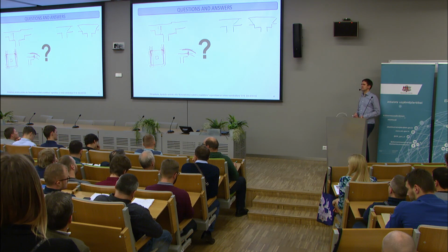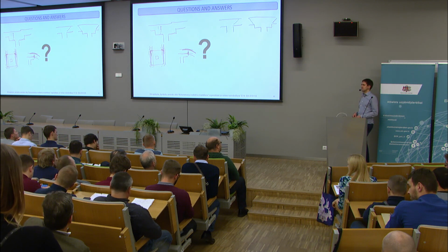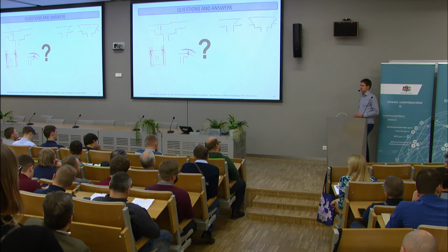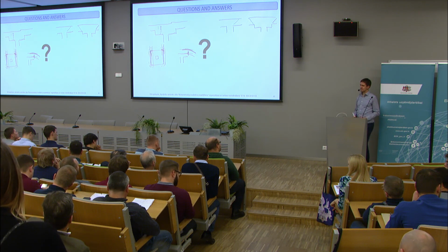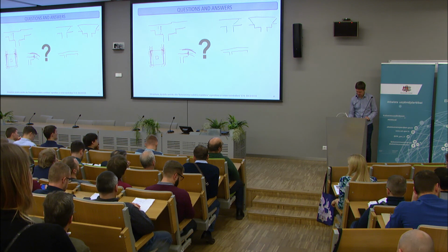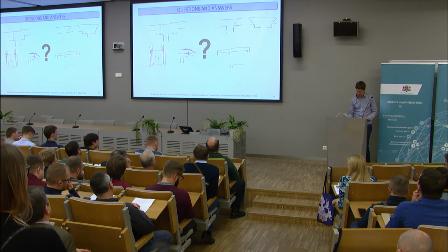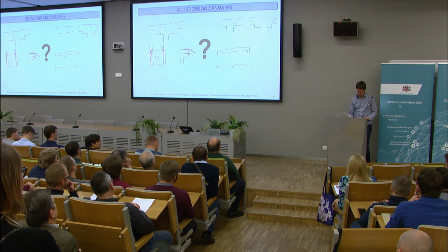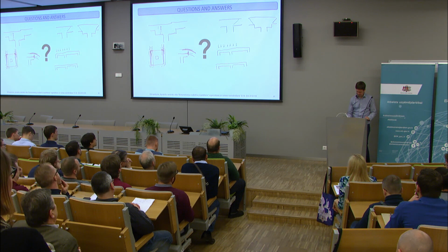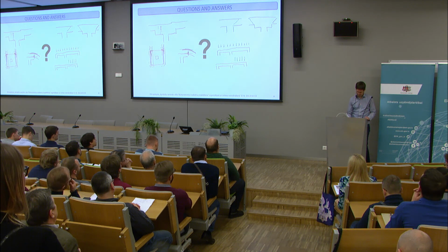That's one case. And in the second case, you can find a situation where you have similar spans with similar load intensities, and there is some moment transferred, in which case the beta calculation from moment and plastic sectional modulus quite correctly predicts the differences in shear flow intensities. But in the general case, it is possible to find a situation where nominally the shear flow through the different parts of the perimeter varies.